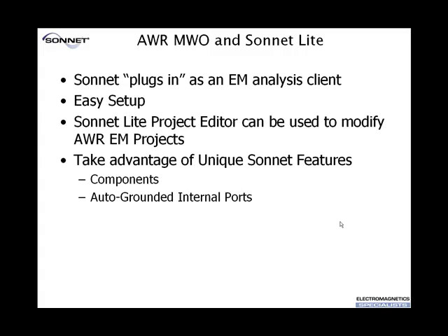It is also possible for you to take advantage of some unique Sonnet features such as components or auto-grounded internal ports, and those objects are wrapped up back in the AWR environment so that when simulation is initiated from Microwave Office to take advantage of the EM analysis engine, those features will stay in the simulation object. Now let's take a look at an example.